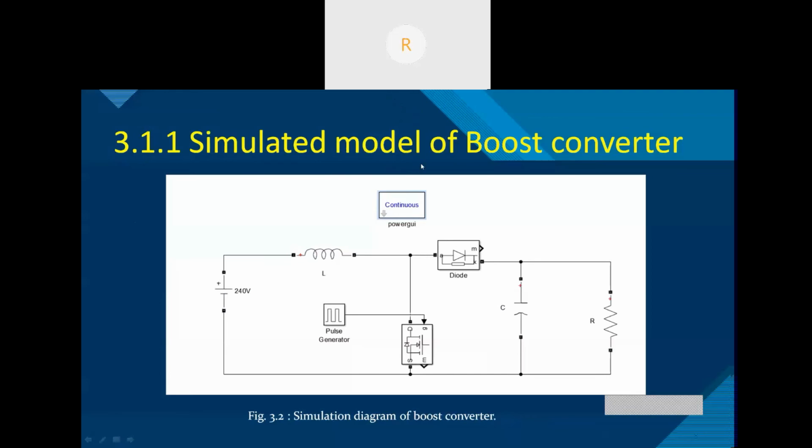Kankan, tell me what are the disadvantages of low power factor? If you have low power factor, then what will be the problem? If we have low power factor, there will be more reactive power. Power factor close to 1 has a low amount of losses, and there will be less total harmonic distortion in the current waveforms.